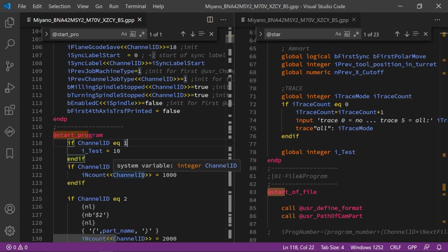Coming back to the question of which one I should use, it basically depends on the Gcode style that your particular machine requires. That doesn't explicitly mean that for the FANUC we will use separated files, for the Mitsubishi we will use order in single file, and for the Okuma we will use mixed in single file. These are not rules. The rule is basically the minimum necessary to use the open and close structure in order to generate proper code.